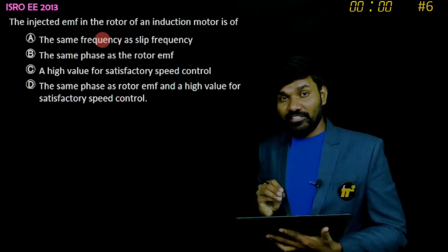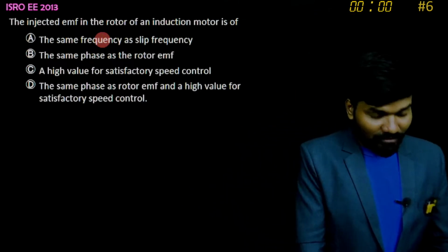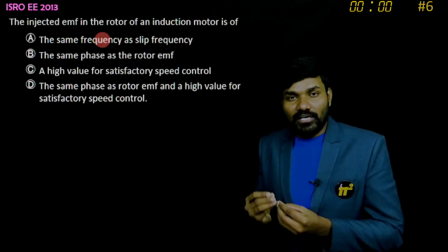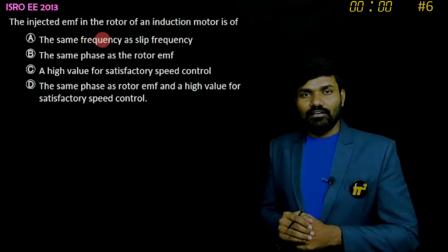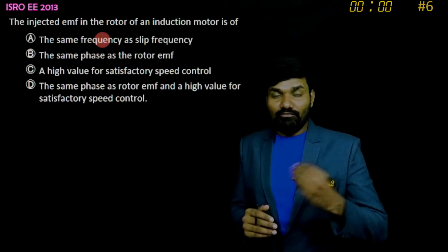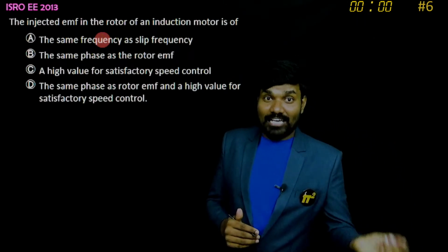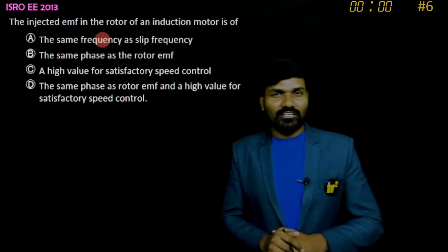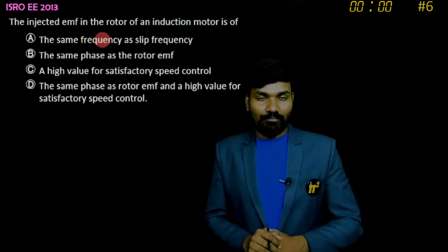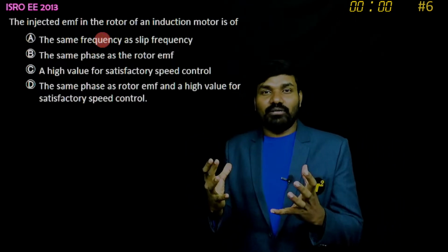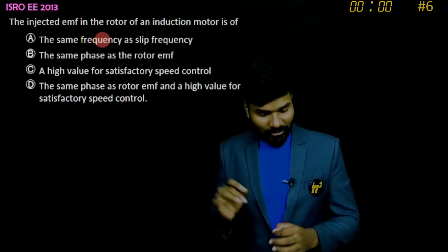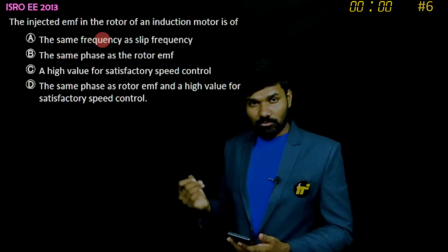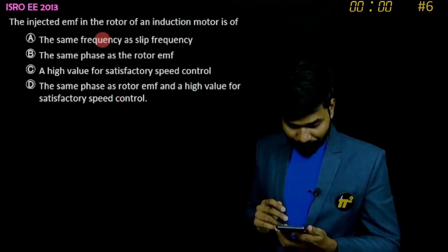That's the challenging thing here, because slip keeps on changing. Slip is not a constant, right? Slip changes with respect to speed. A little change in speed will change the slip, and will change the slip frequency. Hence, you should change the injected frequency also. A very critical and interesting phenomenon. If you see the construction behind it, it will be amazing. If you get a chance to see and experience that motor once, the Schrage motor, or whatever you call it.